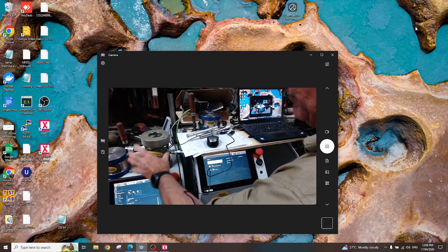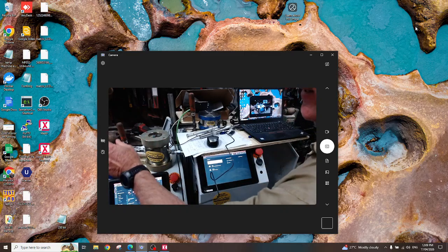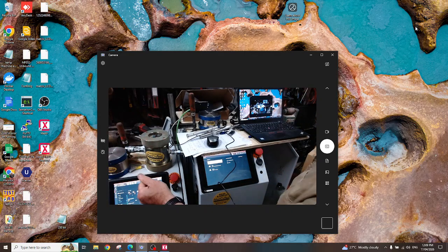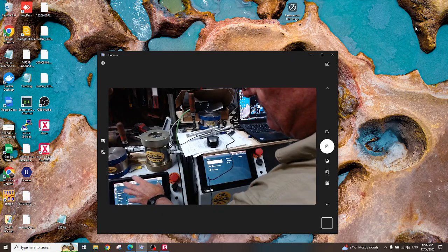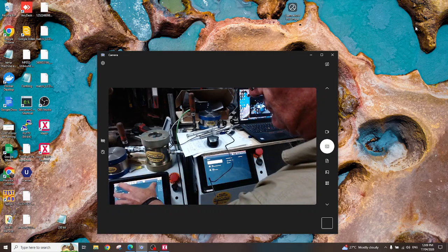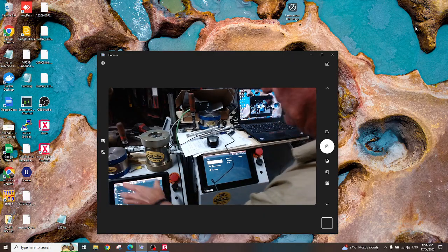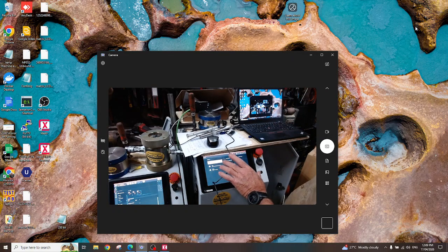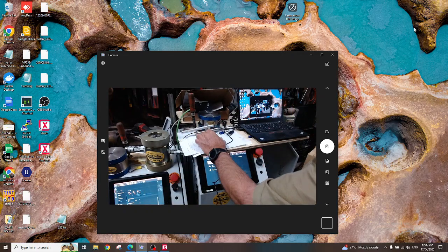This pump unit here has the Hoek cell and two strain gauge inputs. The strain gauge inputs are in a half bridge configuration, so each unit will have two strain gauges and average the two. So this unit here will have confining pressure and two strain gauge inputs. This pump is then talking to this pump to pass the data from here to here for storage and data logging.